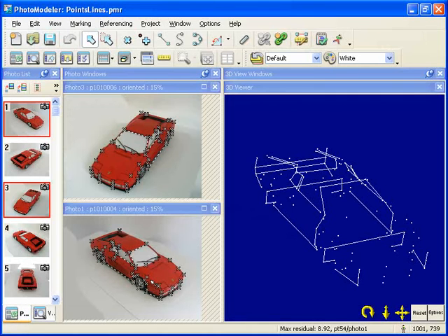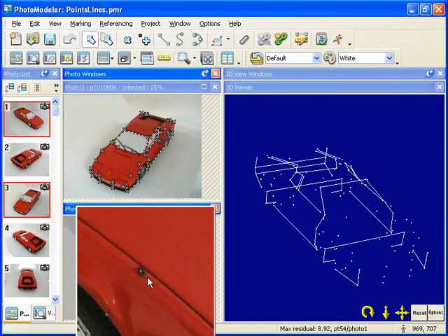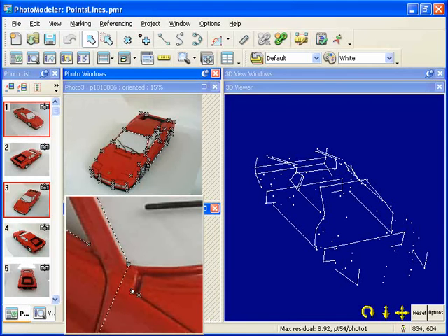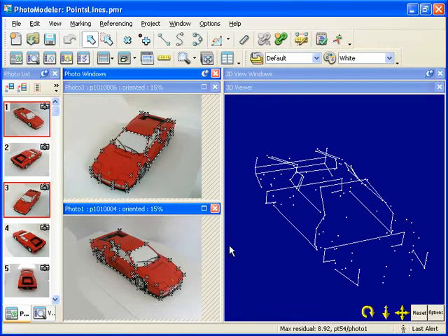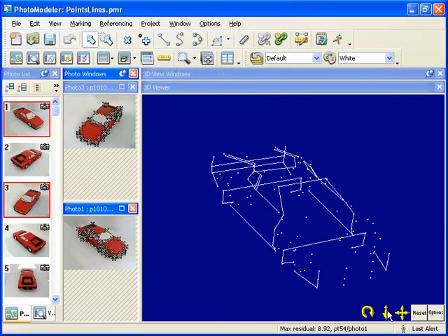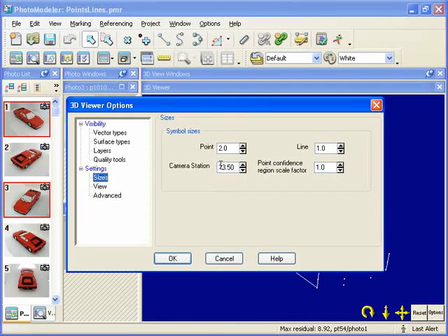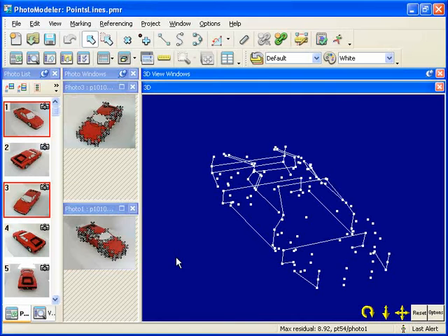You can see that on some parts of the model, target dots have been placed on curves, so we can reference the same point. Other points are marked on natural features of the model. We will start by adding some curves. To make this easier, since we will be using the 3D viewer, we increase the point size in the Options dialog.